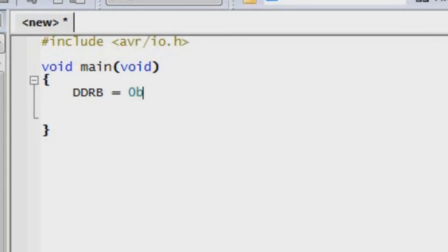So I'm just going to write zeros in all the digits, which mean inputs for all the pins, and I'll change the pin that we're going to be working with after that. So let's do 8 zeros. 1, 2, 3, 4, 5, 6, 7, 8. And pin 0 just happens to be the very last. It happens to be this particular digit here, because in binary numbers, this would be pin 0. This would be how you would start writing numbers. So we want to change that last digit. This is pin 0, and we're going to change it to output.